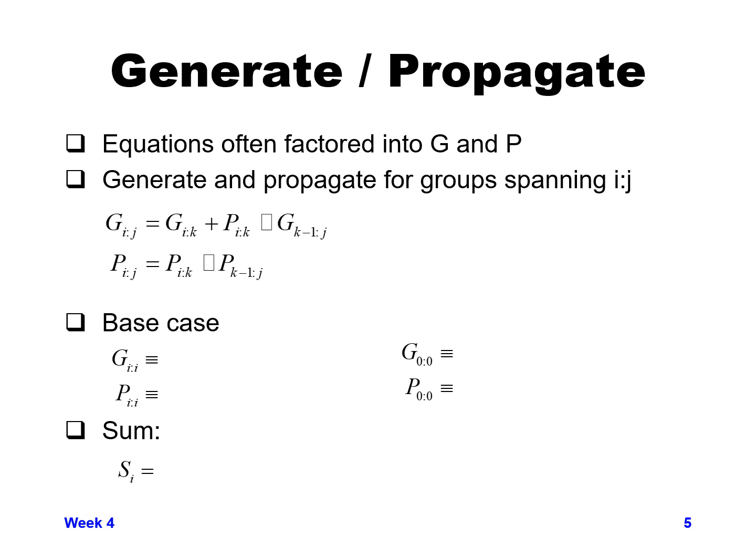Now that we know the general equation over a range of bits, let's look at the base case of just a single bit. For the generate from I to I, it's just generate sub I. So for any particular bit, like bit 8, the generate for bit 8 alone is the A value from bit 8 ANDed with the B value from bit 8. We covered that in a previous slide. And the propagate from I to I, for bit 8, is the A value for bit 8 XORed with the B value for bit 8.